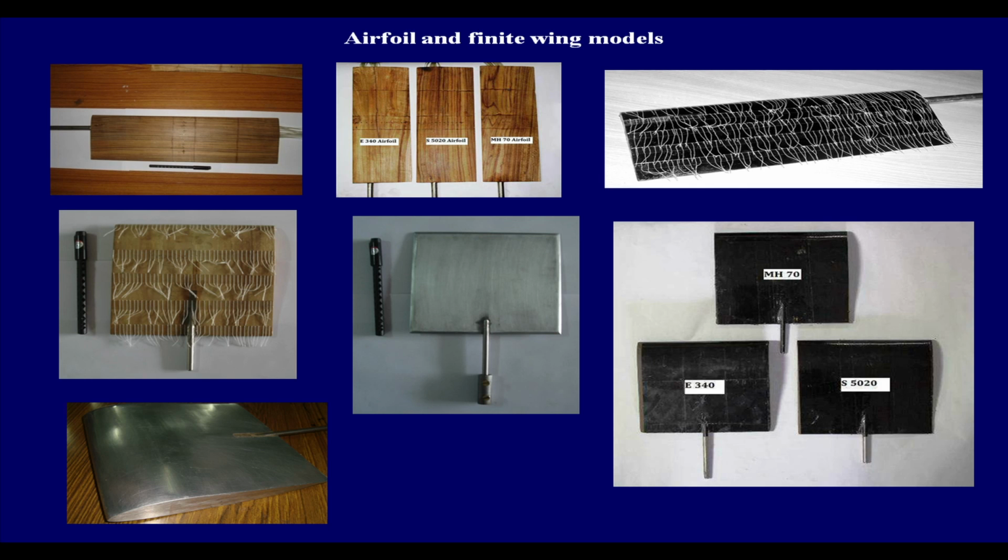You know that in the Reynolds number calculation, those are 2 of the important parameters, and if they are large, the Reynolds number in general will become large. The rest of it comes from the viscosity of the medium. We assume that we will continue to use air, whether it is a big vehicle or a small one, whether it is a wind tunnel or an actual flight, it is all air all over. So, that does not play much of a variable role, that is there anyway.